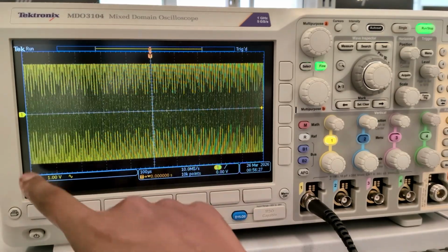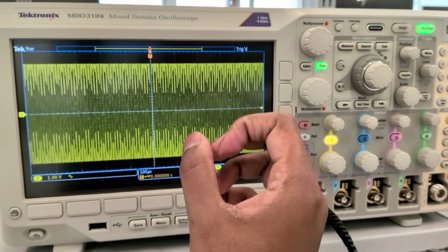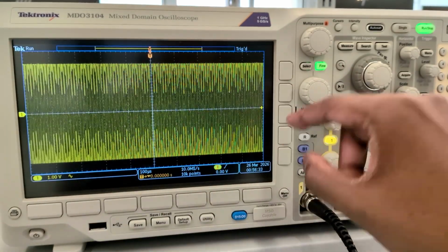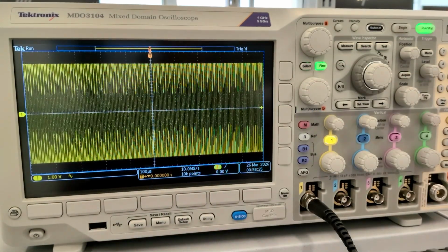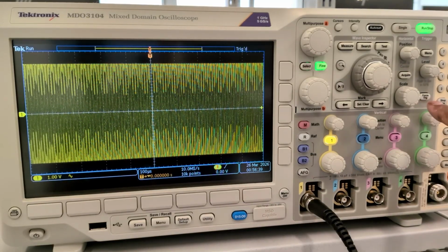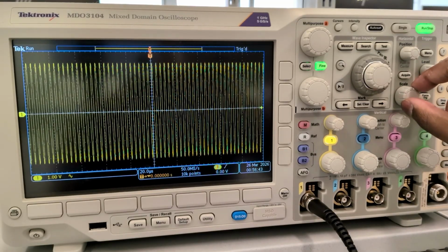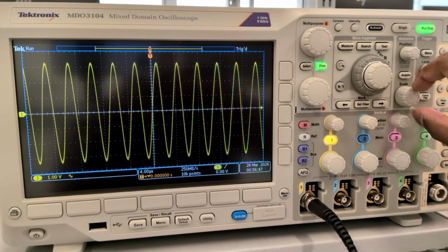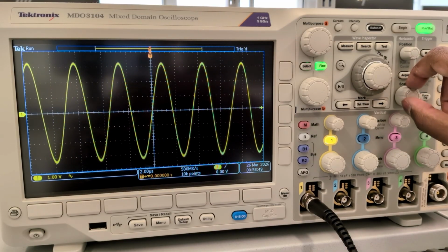So to actually get those 2 to 3 full waves, we need to also kind of zoom in on our wave, because currently we see a whole bunch of repeating patterns here, if we can even make that out in all of this noise. So on the horizontal scale knob right over here, I can also zoom in on that one, and you can start to see our actual sinusoid come into focus.